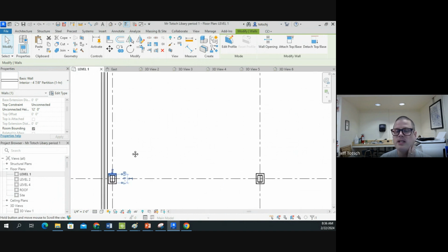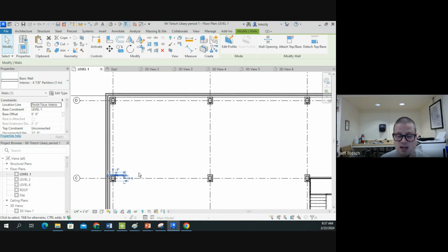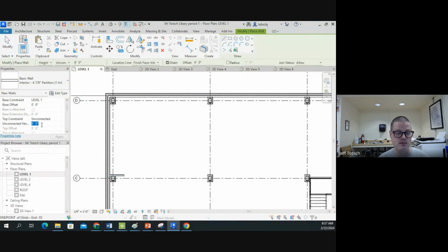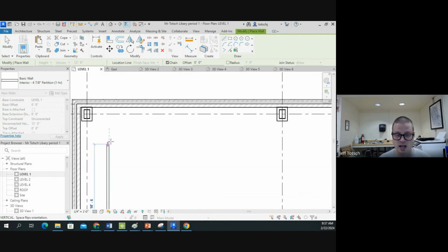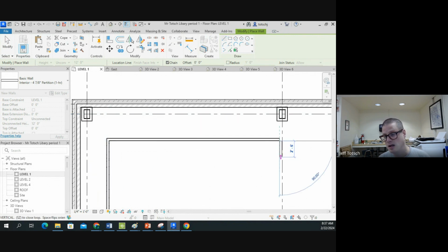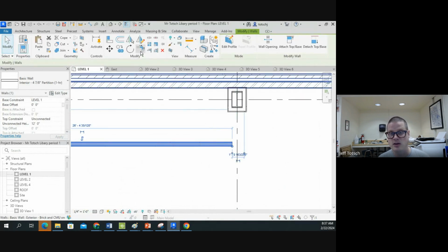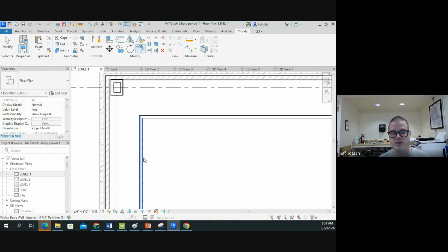If you remember, I wrapped these columns in 12 feet heights. So I'm going to take this wall and extend it there. I'm just going to say my stalls are 5 feet deep. Then I'm going to continue on and create the same wall, 12 feet. I'm setting my height before I create it, thinking about things as I do it. I don't know exactly where I'm going, but I'm just going to rough it out. When I select something and use the modify toolbar, remember I could easily extend things to where I want it.